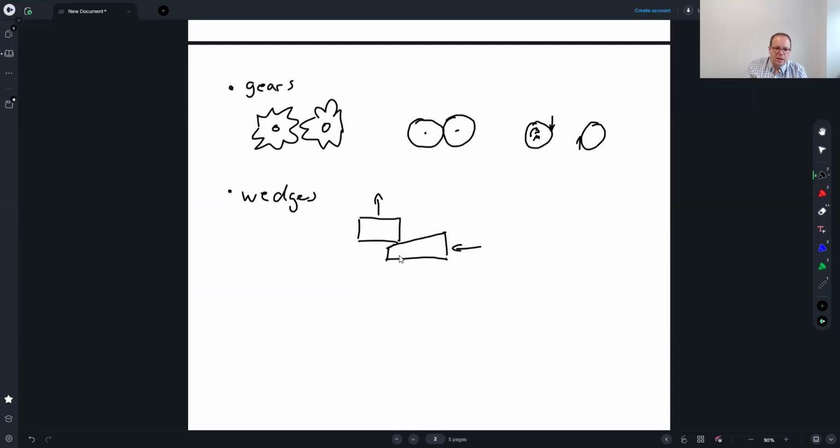The other thing that we're going to look at in some detail are screws, right? How do the forces act on a screw? So we'll talk about that as well. And with that, we're done with our section on trusses and frames and machines. Remember, the idea behind the truss was that we have a whole bunch of rigid pieces that are put together, held together by joints, and forces only act at the joints, which means that all those pieces are two-force members, and that makes my calculations easier.